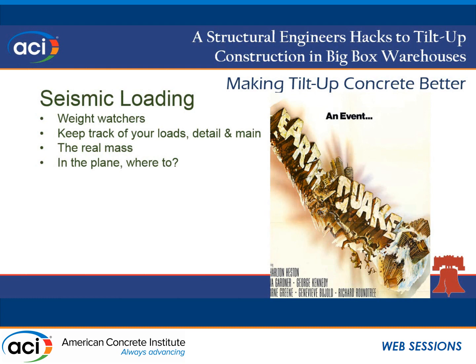And then the last thing in seismic, and this comes up a lot, is when you're dealing with the short wall of a building, right, you're going to have in-plane loads that can be 2.5 to 3 kips a linear foot. You're going to have panel overturning. The question is, how do you deal with it?